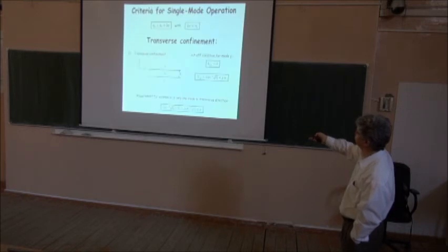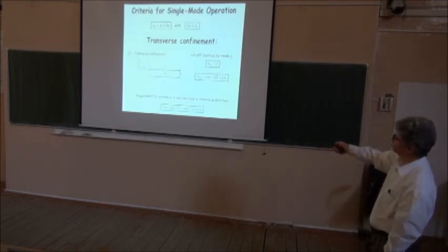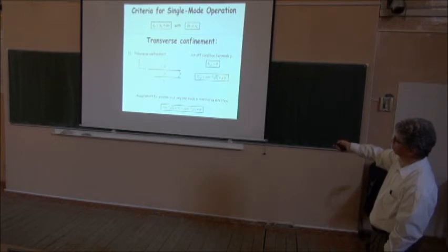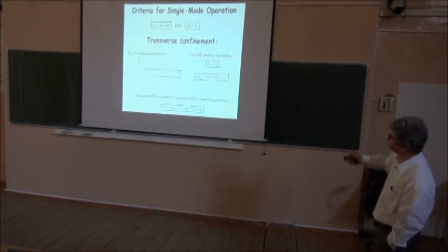So doing that, applying that condition there, we determined yesterday that the cutoff for different modes is defined by the arctangent of the square root of the asymmetry factor plus P. So every time I get V to reach this number, with P increasing by increments of 1 here, I'll get an extra mode.